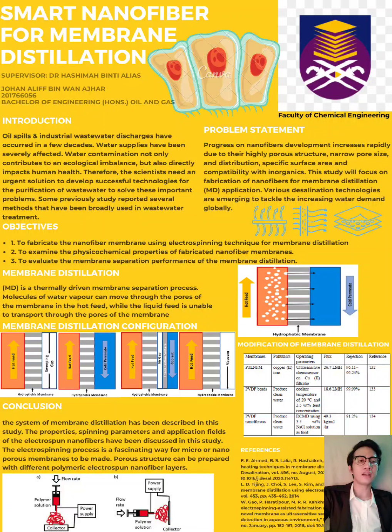Due to its higher thermal and mass transfer resistance, the air gap is known to be the main controlling factor. A pump is applied in VMD to produce vacuum in the permeate part. Thus, a vapor pressure differential is created through the membrane. An external condenser condenses the vapor.